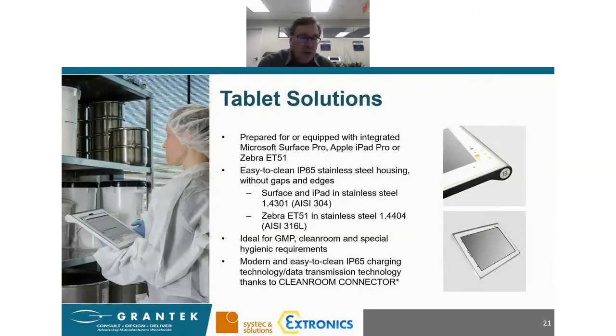They are the actual unit from each of the manufacturers put into a stainless steel case. I'll bring it over now because I want to show you how they charge. We put the actual unit in the case. The charging, you want to make sure that you have maintained the integrity. You'll see the charging here, the connectors. I'm not sure how well this comes through on a camera. This is keyed mechanically. You'll see a bump at, say, noon, and then down below one at, say, 5 o'clock and 7 o'clock, which forces this to connect in only one way.